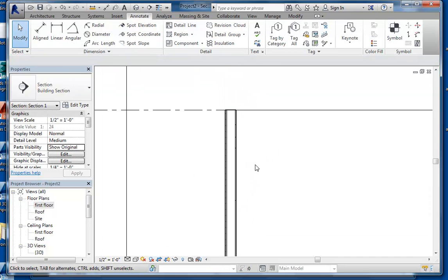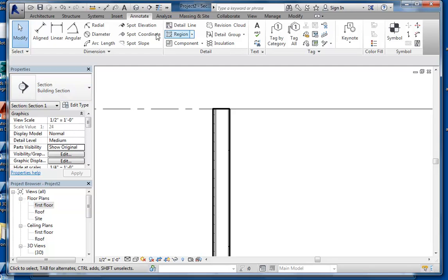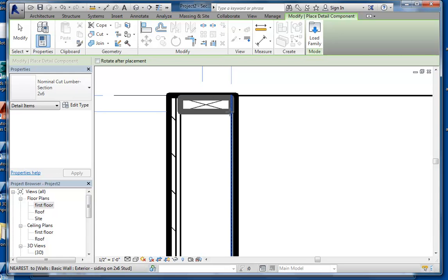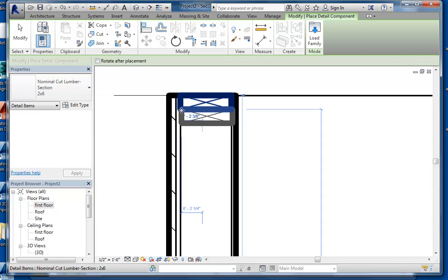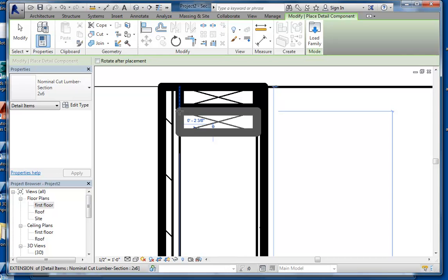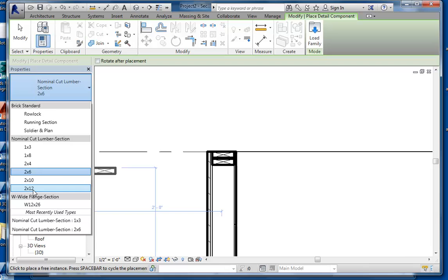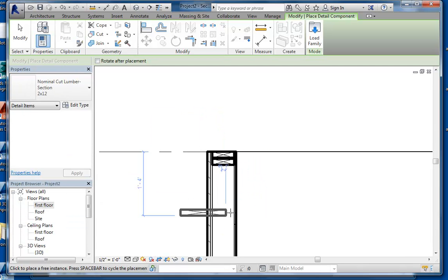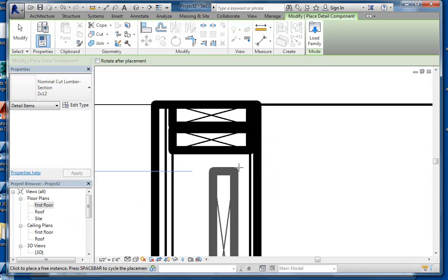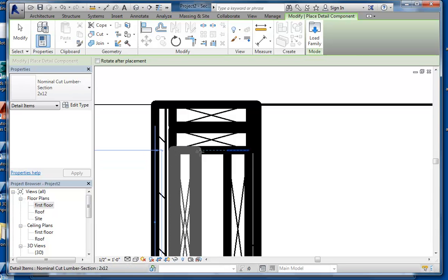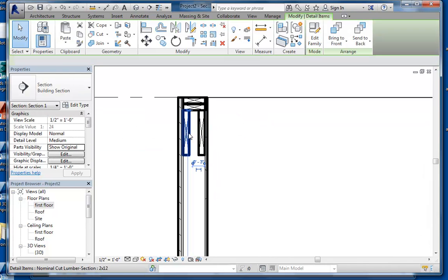And then up at the top, I would put in my 2x6 double top plate. I'm going to take advantage of being able to snap to these points. And then below that, I might have my 2x12 header. But remember, I used a 9-foot ceiling, so I'm going to have a 2x12 header here and here. But then I'd have cripples in between those two things.